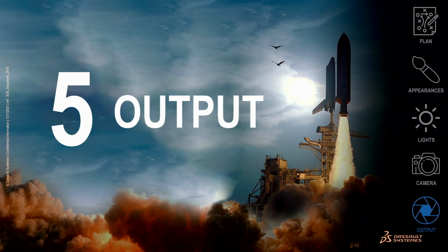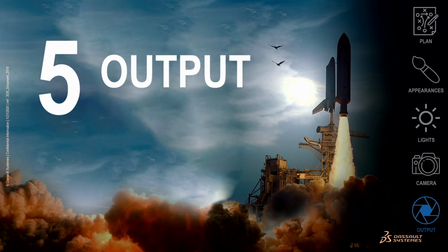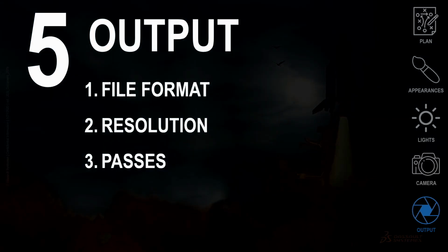Okay. So the next section, once we get things set up, is how do we actually get it out of Visualize? And to get things out of Visualize, there's, again, 3 things that we mostly need to be aware of. What file format do we want to use? What resolution do we want to use? And how many passes do we want to use to get this spit out?